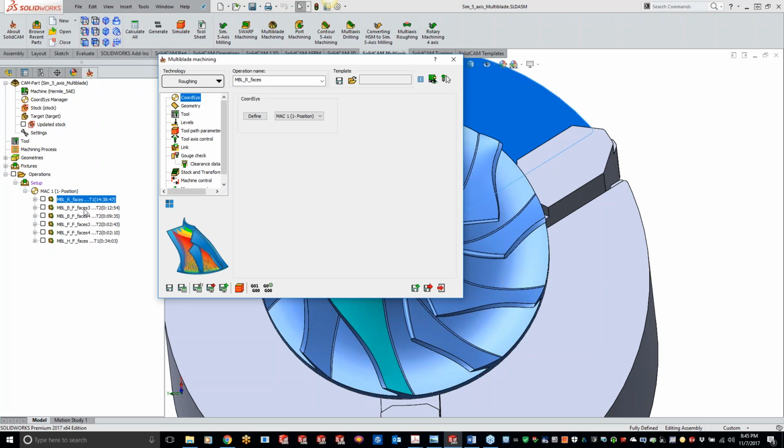No doubt. It's always, Kevin, a balance between, you know, speed of getting the material on the machine and off, and what types of finish you need or require, right? And that's where playing with the software a little bit, you can really fine tune that. Yeah, absolutely. And like I said, the nicer the finish looks, the more cycle time you have, unfortunately. But you just got to find what you're looking for versus, in return, the cycle time. So. Yep.